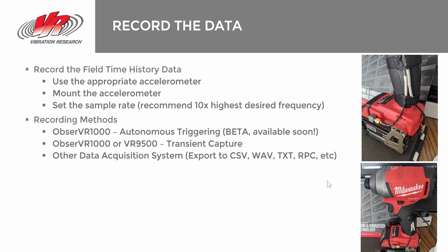Most of the time when doing shock type acquisition, the best bet is to stud mount your accelerometers, and if possible use a grease or non-compressible fluid in between the accelerometer and the mating surface itself. Today I'm really not expecting extreme high frequency ranges, and I know the relative peak accelerations that I'm going to get, so I'm just going to use some 10 millivolt per G triaxes, and I have super glued them to my drill rather than drilling holes into them.